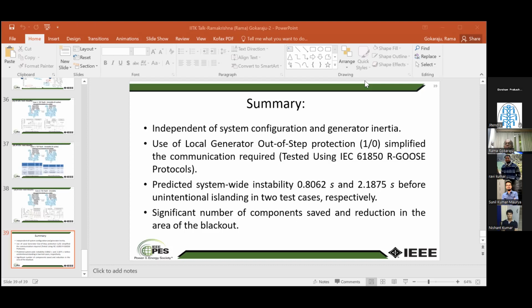Sir, actually, when we draw the power angle curve, usually we tell that whenever the angle goes to 180 minus delta, we have 2 points where we can achieve the load generation balance, delta and 180 minus delta. So it may go above 180 minus delta sometimes, which is still less than 180. In textbooks, we tell that if it crosses 180 minus delta, it would be an unstable point. That's why we do not consider that point as a stable operating point.